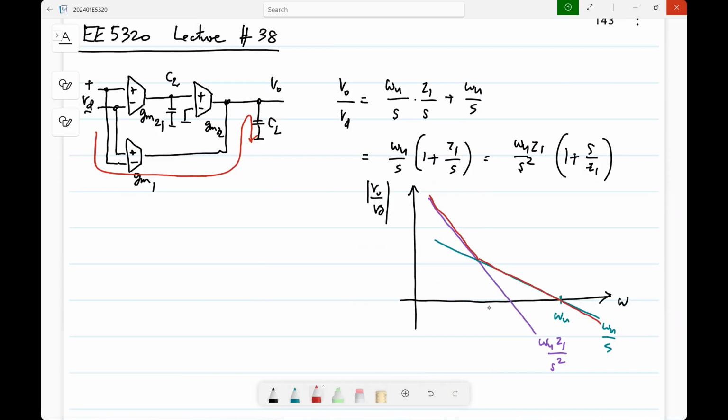that. Okay. So what I was saying was, if your AC coupling corner is below this, then you're not going to be affected by the fact that you AC couple this stage, right? Now, of course, in reality, you do have a finite DC gain. So what happens is that at low frequencies, the gain will get limited. Okay.